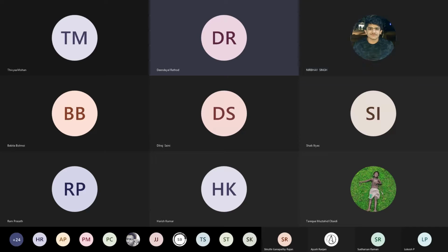So in the triaxial test, we are applying the all-round stress, that is sigma 3, the minor principal stress, and on the top, sigma 3 plus one more stress, the deviator stress, giving sigma 1. Sigma 2 we are neglecting here.